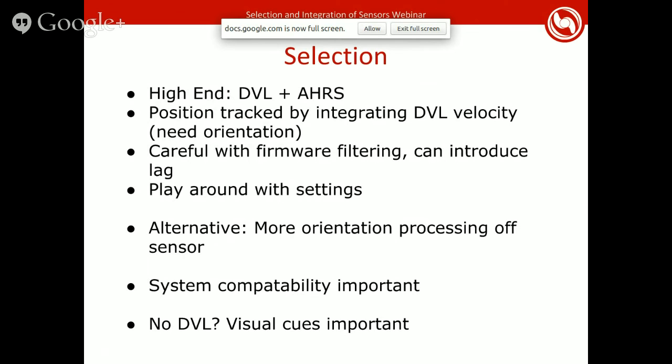It's also nice to be able to fully characterize your cameras so that if you see an object in frame, you'll know exactly how that corresponds to the world position of the object. And that can help with not just velocity estimation, but other things like localization of objects and localization of the sub itself. A lot of fancy localization algorithms like SLAM and other cool robotic algorithms use camera extrinsics and the intrinsic matrix to use the visual data as efficiently as possible.